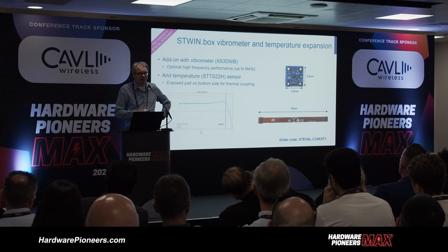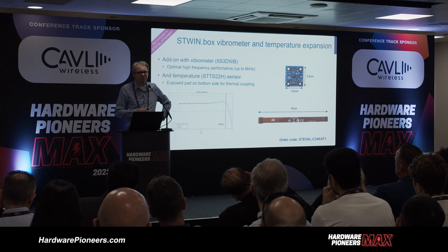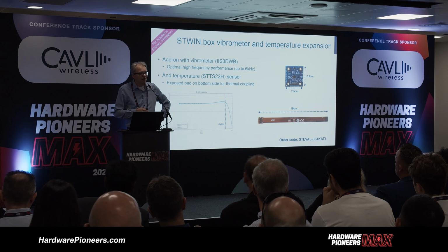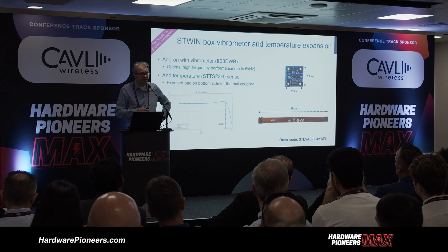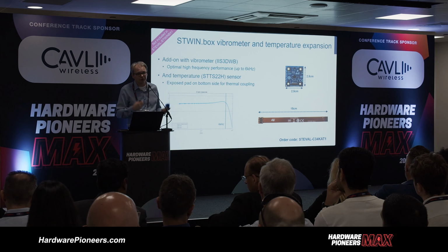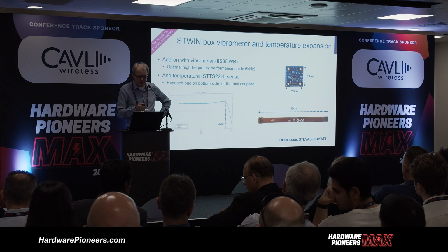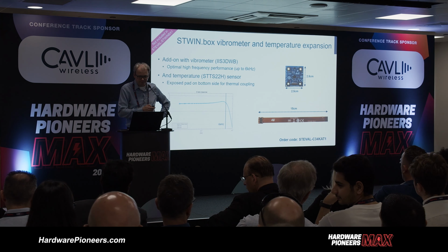And this is indeed needed if you want to go up to 5-6 kilohertz of bandwidth. And then this should be also taken into account in the final end product design, to make it very robust, avoid any resonances, and then in some cases some have even remade this board and plastics from aluminium, for example. So make it very accurate to capture the data logs also very accurately in the very beginning.